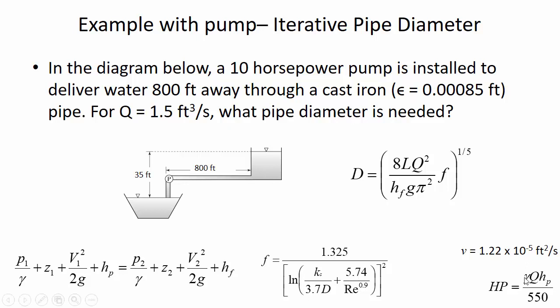But if we have pounds per cubic foot for the gamma and cubic feet per second for the Q, and if the pump head is in terms of feet, and then we divide foot-pounds per second by 550, then we get horsepower out of that. So this is both the power equation and the units conversion from foot-pounds per second into horsepower. That's this lower right equation.